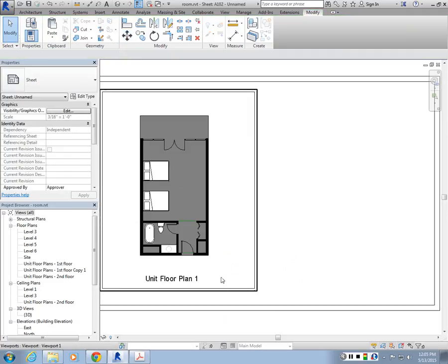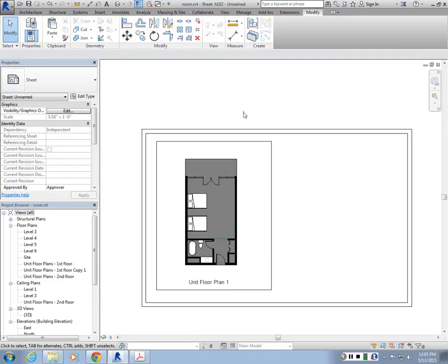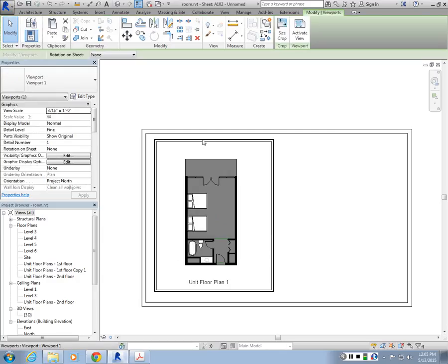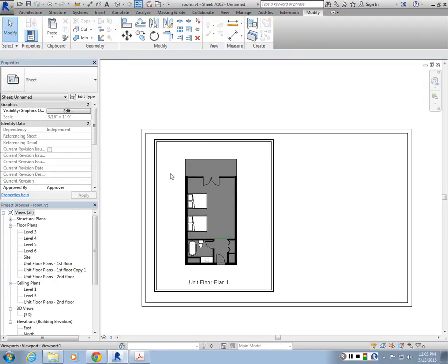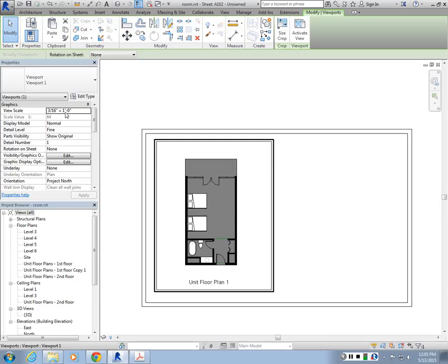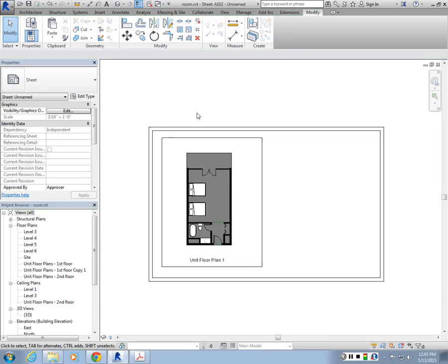This is kind of the nice thing about Revit, because you just model something and you can create multiple drawings at different scales of the same model, and it will filter the information and adjust the line weights accordingly. So you can find a scale where your unit occupies a nice area on the sheet, and in this case 3/16 inch equals 1 foot worked fine for me. Okay?